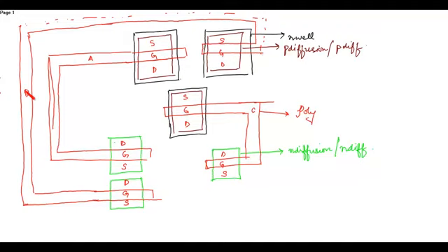Now after drawing the gate terminal, now draw the source. The inputs are given ABC. Then the sources of the PMOS is connected to VDD. So connect these two. We'll make an extension here since there is no space, otherwise we would have connected like this. Okay, they're connected to VDD,